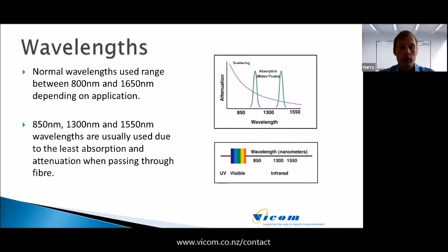You've then got a band between 1625 nanometers and 1650 nanometers, which is specifically allocated for maintenance purposes only. And I'll chat about that range shortly when we discuss OTDRs and the like later on. Basically though, you can have tooling that's 1625 or 1650 nanometer wavelengths on with a filter, and you can then undertake maintenance tasks and testing without interfering with live signals in the fiber, and the live signals in the fiber not interfering with your test set.